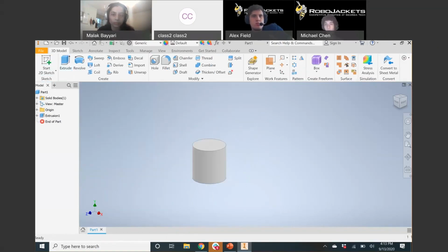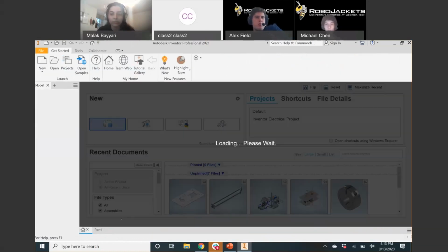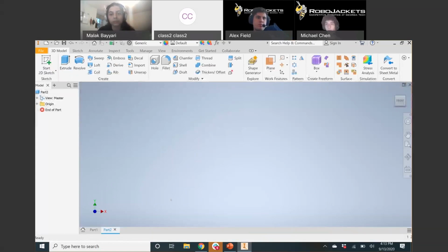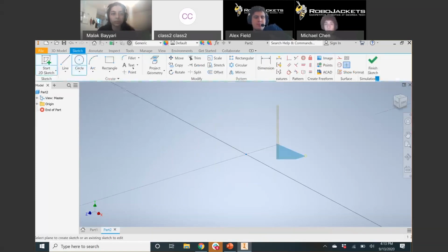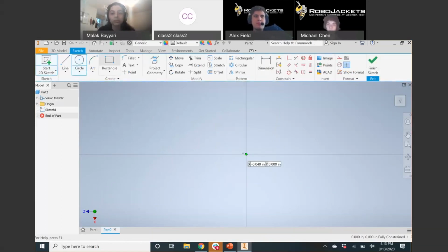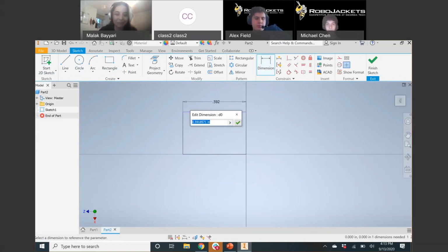For those of you who have not messed around with Inventor before, if you noticed, the sketch was still purple, but you are still able to do operations such as extruding or cutting holes, even if the part isn't fully dimensioned. We don't recommend doing this, but for all intents and purposes, this will work for now. Yeah, no, for sure. Don't do what I'm doing. I'm just kind of messing around now.